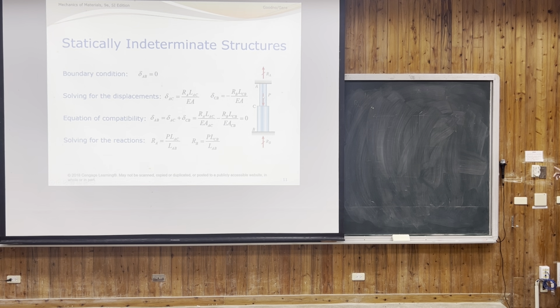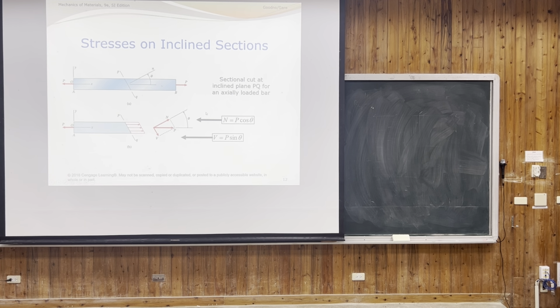And this kind of question is like the elongation between A and B equals 0. So you write delta AC added by delta CB, and calculate the different elongations, and you know what the reaction force in A and reaction force in B are. And this is, I think you will have to know, a basic.